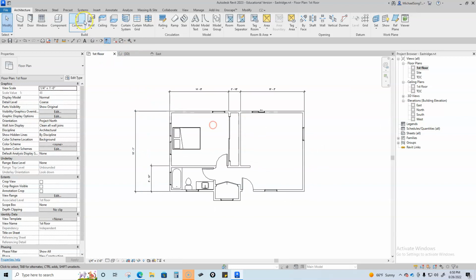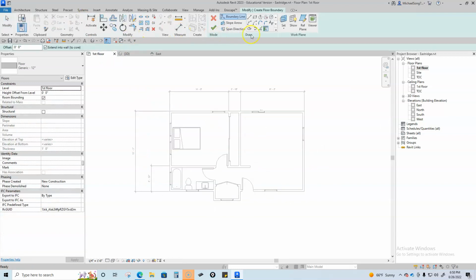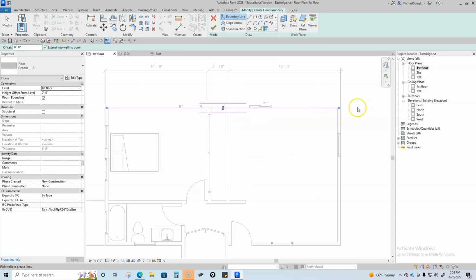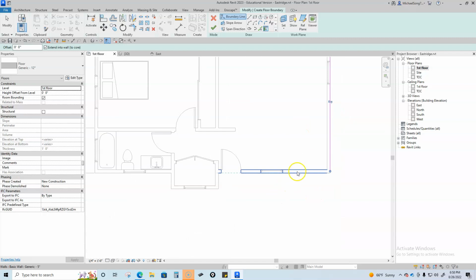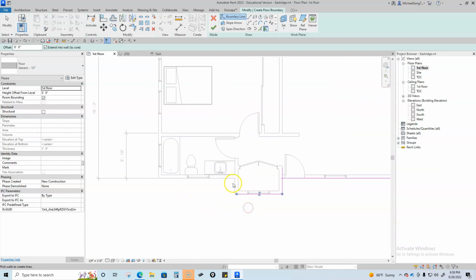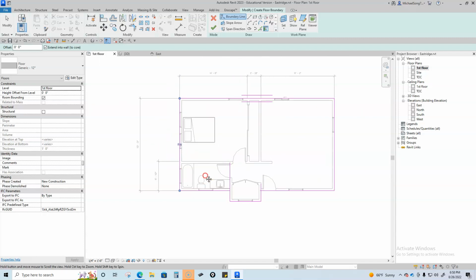Another way to create the floor is to use the wall tool. So that means you're doing the locking and creating at the same time, basically. So it's saying, if I pick that wall, it says now it's attached to that wall. I could actually push the floor to the outside or to the inside, whichever way you prefer. And so now Revit already knows this floor is connected to the walls that I'm selecting.